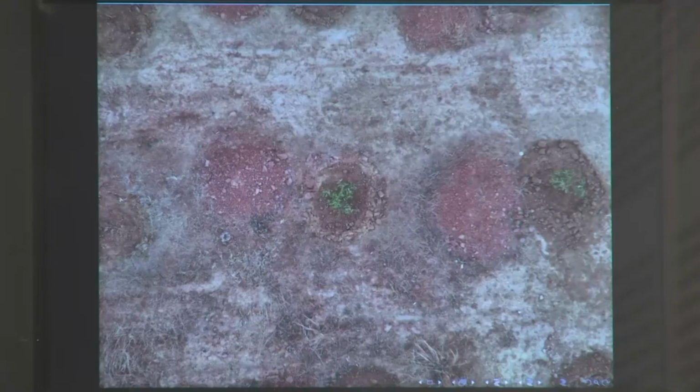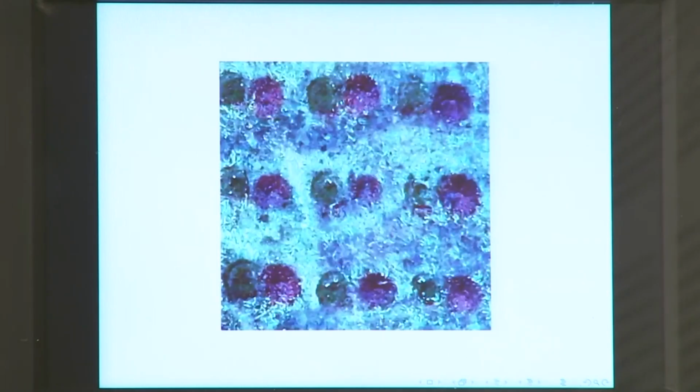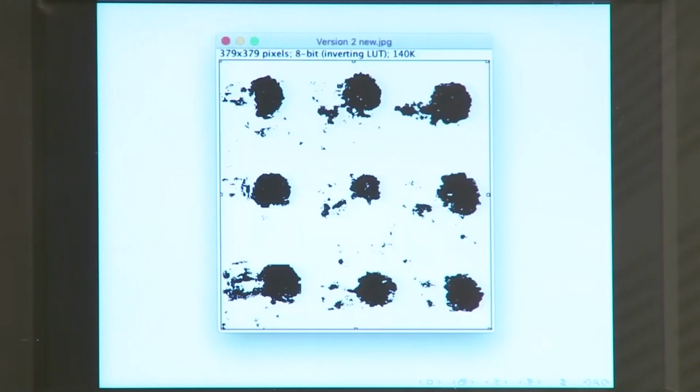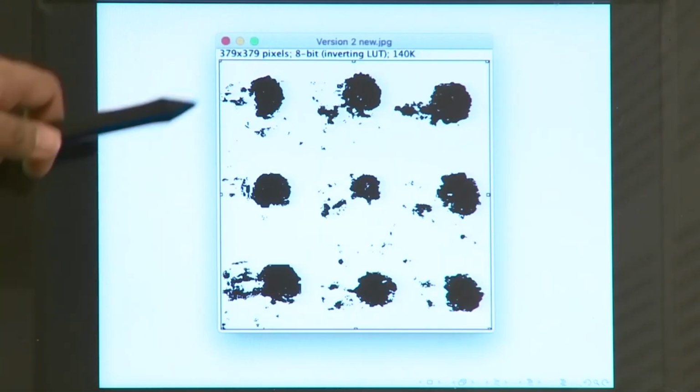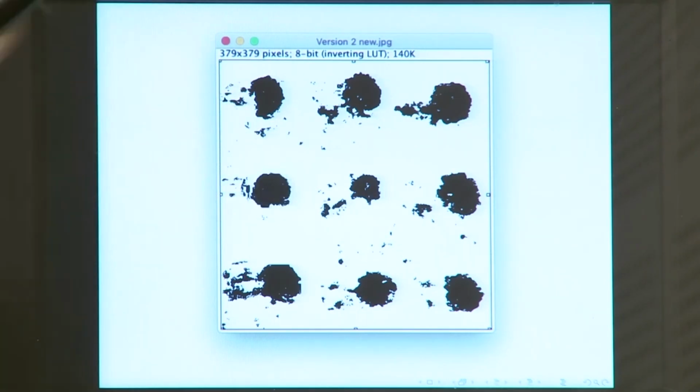Now, another good thing about photogrammetry is that you can alter these images, you can process these images for other applications. So, for instance, this is a section of the plantation that we processed. So, in the case of this processing, we increased the contrast of these points, then we converted them into a binary image. Now, a binary image is either 0 or 1, and in this case the dark spots are 0, the bright spots are 1.